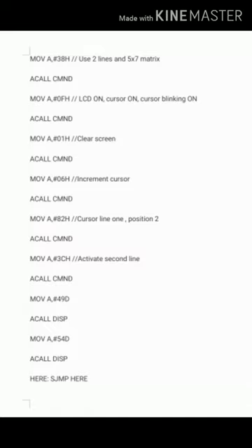Second command, I told you that 0FH will turn the display on, put the cursor on, and also make the cursor blink, right? If you don't want that cursor blinking, there is also another command on the list, you can go find it. That particular command can also be sent instead of 0FH if you would want. So initially you have sent 2 commands and you are calling the command function routine, right?